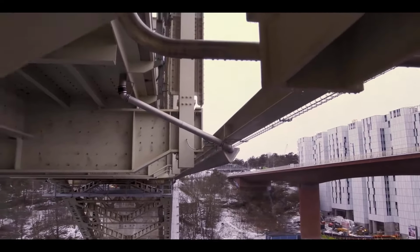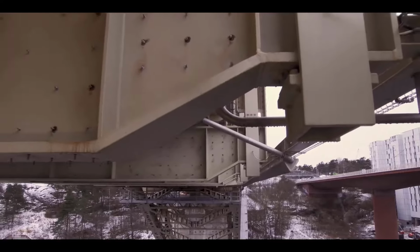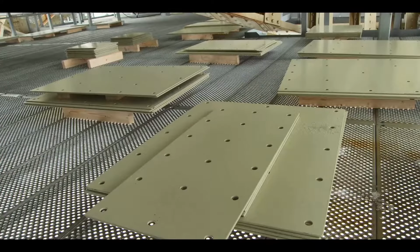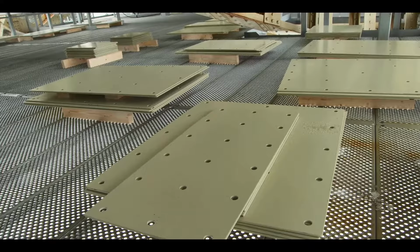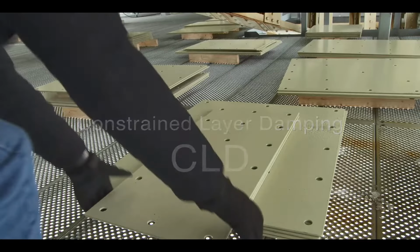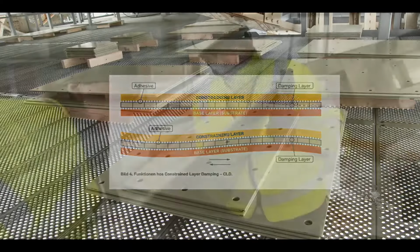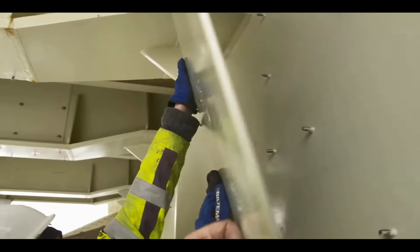All measures to be taken must occur below the bridge deck to enable normal service to proceed. Vibratech chose to test a noise damping technique known as constrained layer damping, CLD. It entails that a noise damping material is pressed, constrained against the steel structure of the bridge. The vibration is caught between the steel plates and dampened in the constrained layer. In order for this to work properly, there must be full contact between the surfaces of damping material and steel.